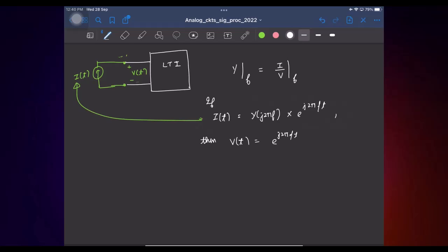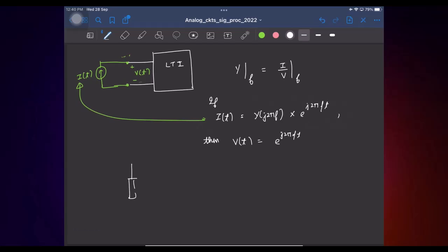Substitution theorem. Everyone is aware? It simply says if you have any network, any element, you find the voltage across it, and if you know the current through it, I can replace it by either a current source of that value or a voltage source of that value, and nothing else will change. And by the way, do you think the substitution theorem is valid for any network or only for linear networks? Any network? Only linear networks? No one is supporting linear networks.